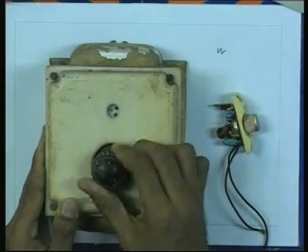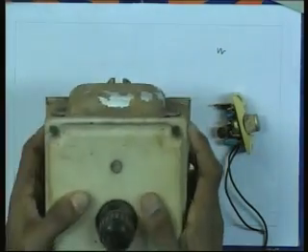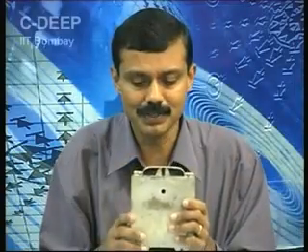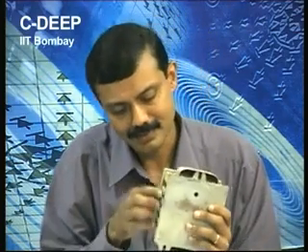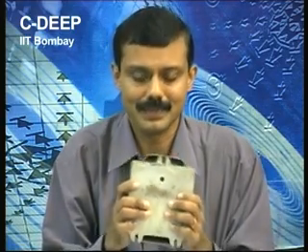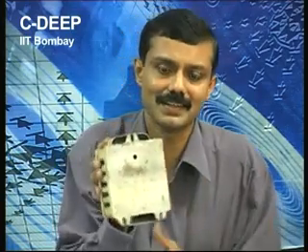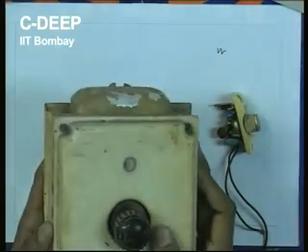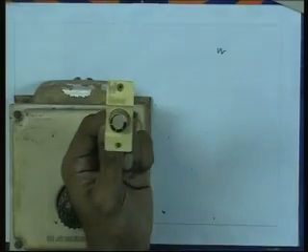If I keep it in very low speed, after some time this regulator becomes very hot, extremely hot. That's the reason we have to mount it on the switchboard, and there are a lot of openings here for the air to flow, to cool the entire setup, because there are resistors inside. It becomes very hot when the speed of the motor is very low. In other words, when you introduce the resistance in the circuit, it becomes hot. Very rugged, maybe. See, here is another regulator. You might have seen a small, elegant regulator.